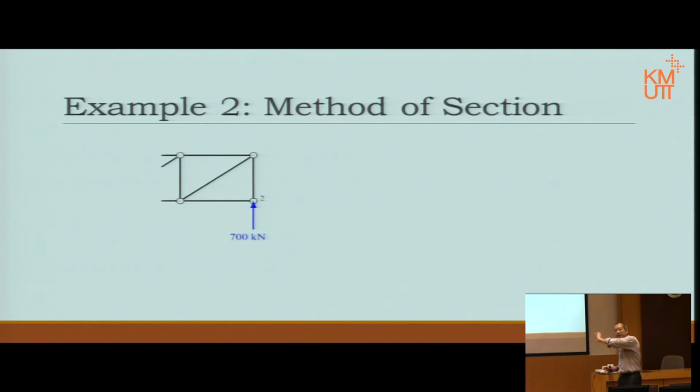Okay, and this picture has fewer forces. Once we cut it, of course this is the line of the axial force. Now, this is the way we look at the forces. If I want to know any line of forces, I find a point where I take moment and then consider which way the force goes. The first one here, I look at